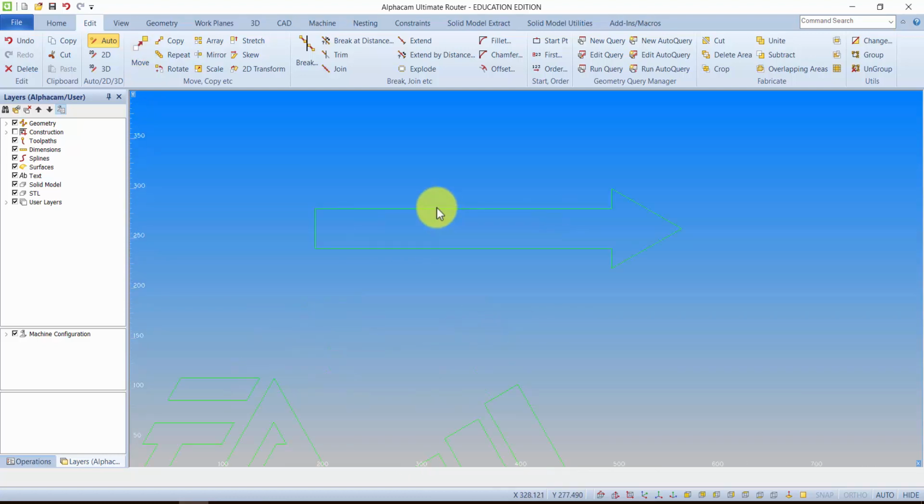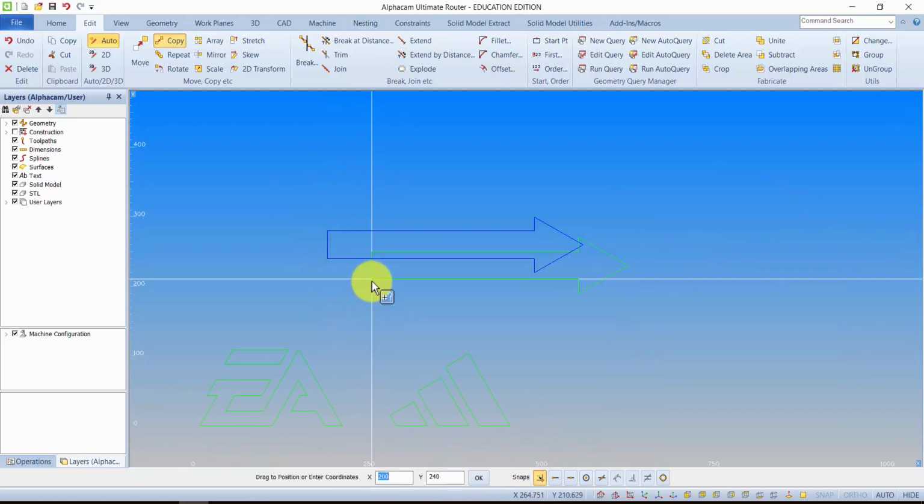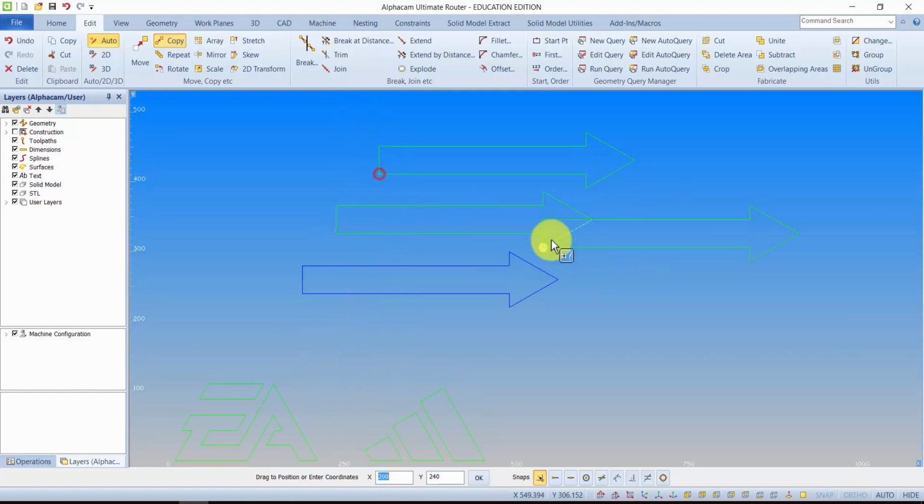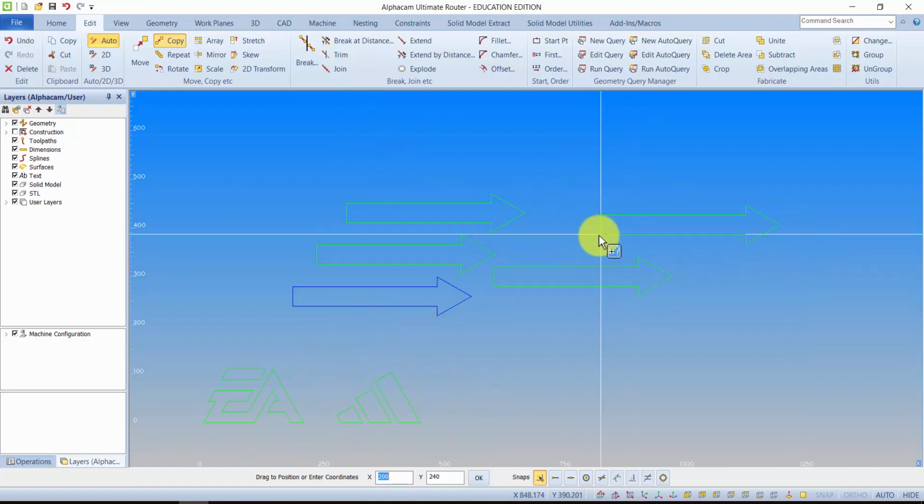So we've already practiced the move command. Let's now use the copy again. I know we've practiced these already, but let's just practice them one last time. You'll notice when I select copy and then try to select the artifact, it's all grouped together in one continuous loop, which is good. So I need to select that, and you have to then tell the computer you're finished selecting, either by right clicking or press finish. I'm going to pick it up from here and then drop a couple of copies around the place. There we have the copy command. Tap escape to close the command.